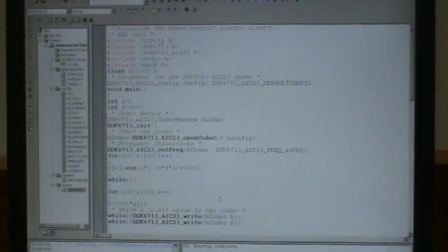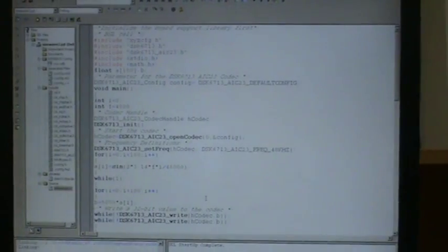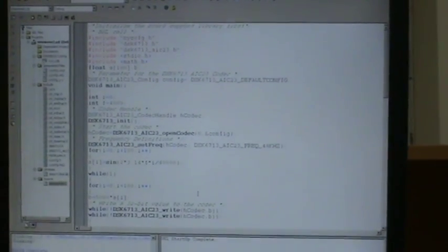It includes all the header files, with your open configuration and close configuration, and also the frequency. We can add or remove frequencies, like 48 kilohertz or 24 kilohertz, and the final sampling frequency is your f by fs. Fs is your 48 kilohertz, 16 kilohertz, or anything, depending upon the AIC codec. It's a simple code for sine wave generation.